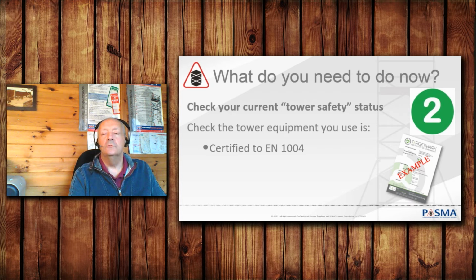Number 2, things you also need to be checking. Check that any towers that you own are certified to EN 1004. If you have towers which complied with old standards, old national standards, or standards like HD 1004, then we would recommend that you think seriously about replacing them.